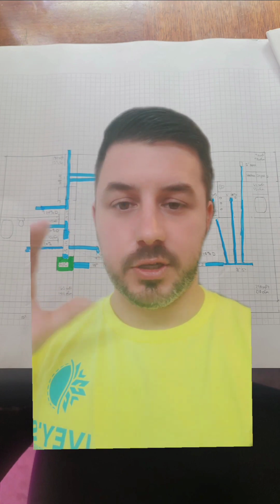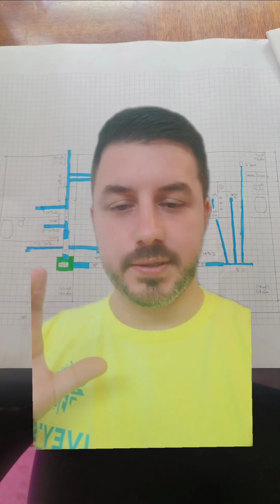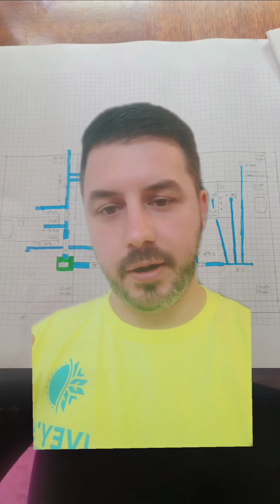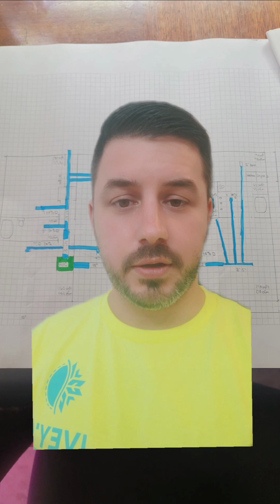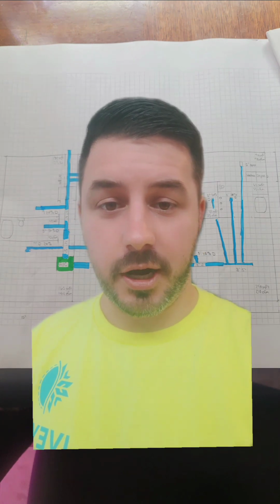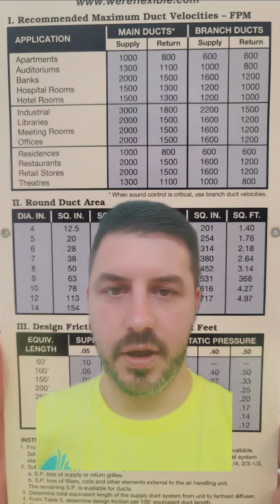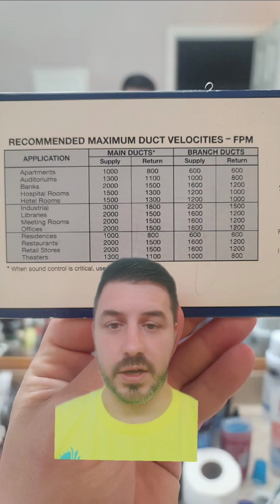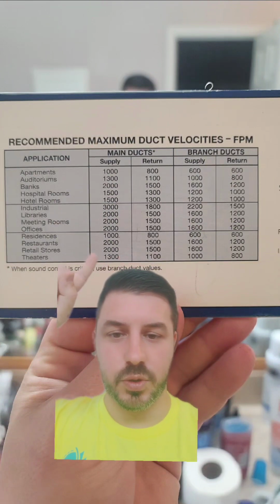So you can actually, this will tell you the smallest pipe that you can design this at, so that way if it's feeding a room, you know you're getting an amount of airflow. It's a cost-effective way to make your bids. A 7-inch pipe is cheaper than an 8-inch pipe. An 8-inch pipe is cheaper than a 12-inch pipe, etc., etc. It's cheaper to insulate. It's less stuff to carry around. You get the picture. If you're going to look at the velocity of the air, this is what they recommend for flexible duct. If you want to look at the velocity of metal pipes, this is it as well.